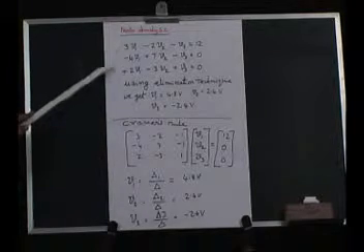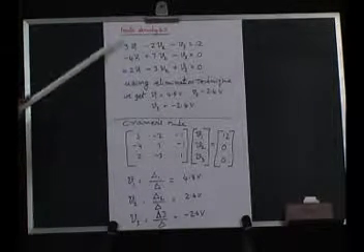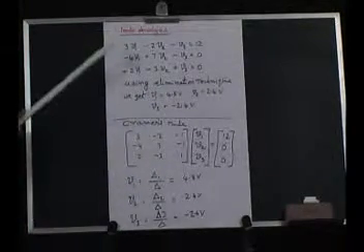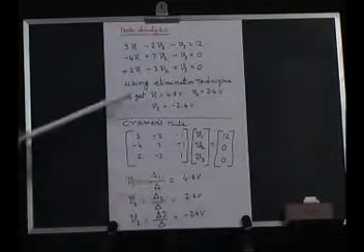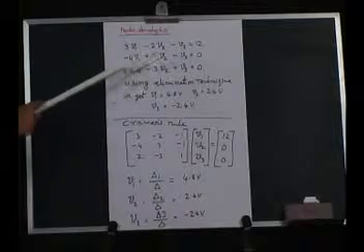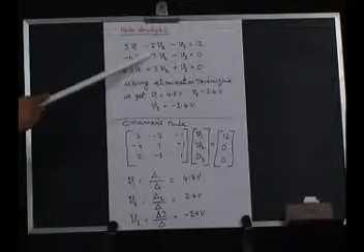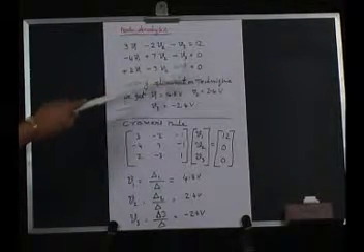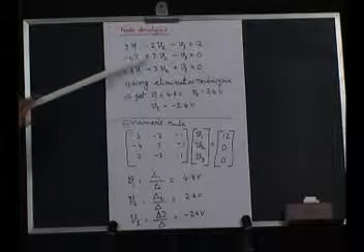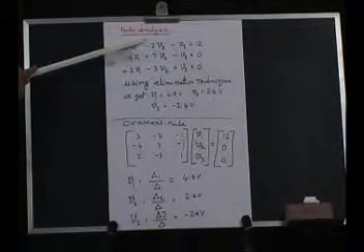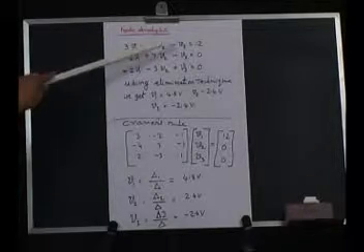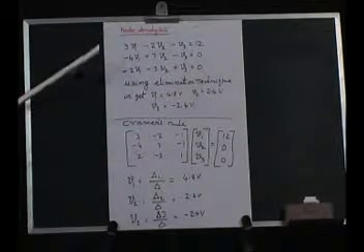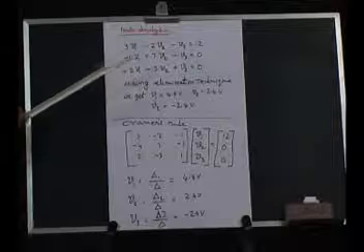The same equations I have written here again, and then we can solve these simultaneous equations by the elimination technique or by Cramer's rule. For instance, in the elimination technique, we first of all can eliminate V3. Suppose we add these two equations, then plus V3 and minus V3 becomes 0. So, there will not be any V3, and you have an equation in terms of V1 and V2. Suppose you take the first equation and the second equation and deduct one from the other, V3 is again eliminated. You have 2 more equations in terms of V1 and V2.